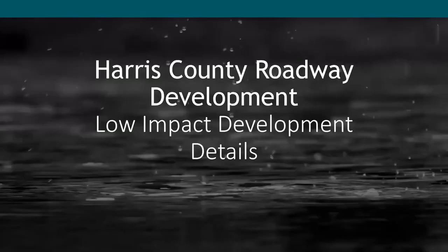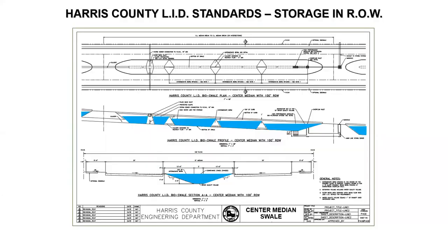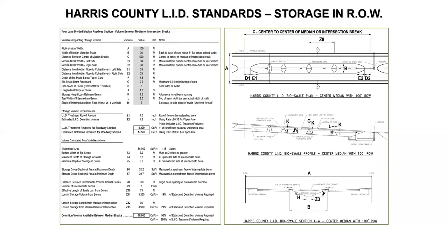And then lastly, if you guys want to reach out to me, I would love to share with you the Harris County Roadway Development. They actually put some really good LID details together on how to apply these vegetated systems for roadway projects, which can also be used for parking lots and other applications. And so this is an open source material. And so they have different design criteria. They have a really nice spreadsheet calculator that allows you to manipulate the size of your bioswale, bioretention, whatever you want to do with it.